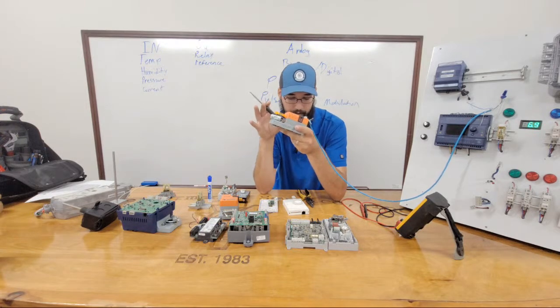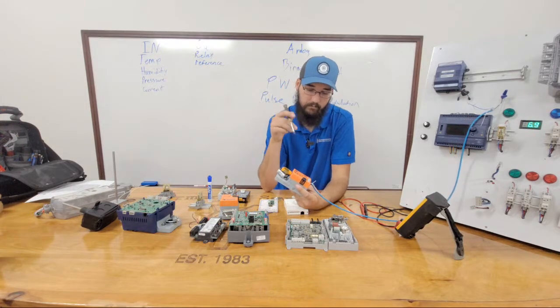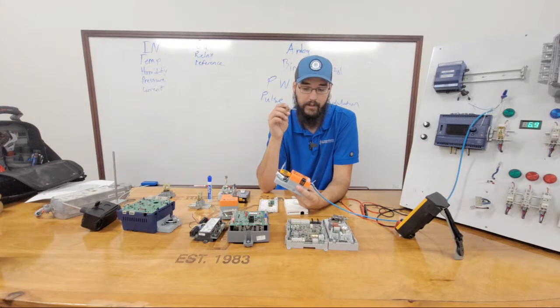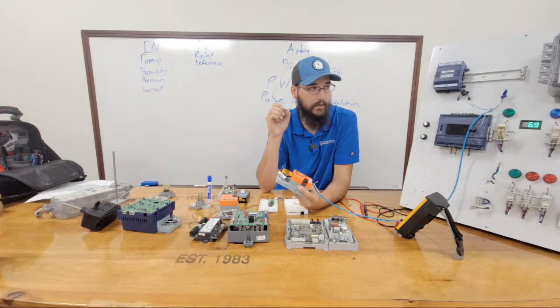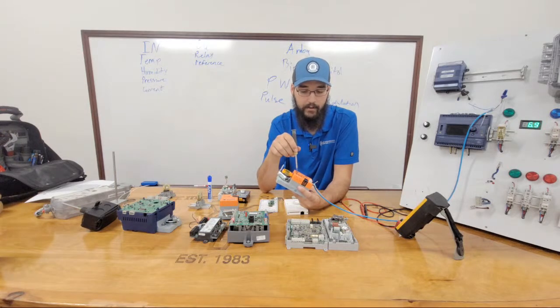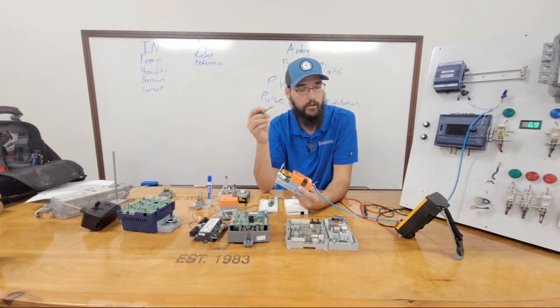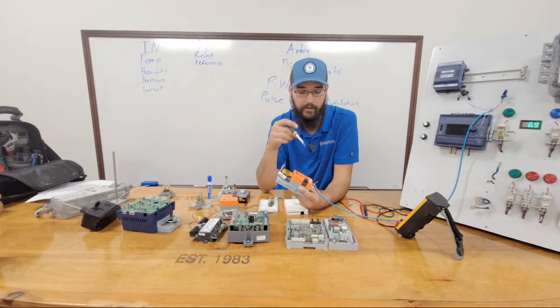Without going crazy into logic programming, the speed of this actuator is important to a programmer, because if his PID loop is calibrated to a different actuator, it can overcorrect faster than the actuator can actually respond to the signal given.